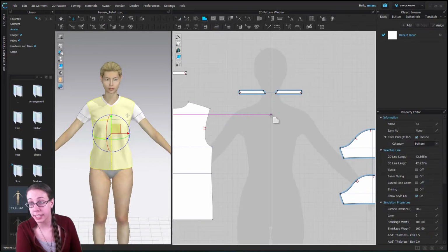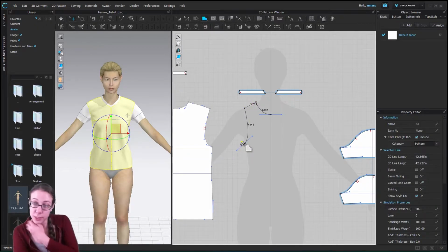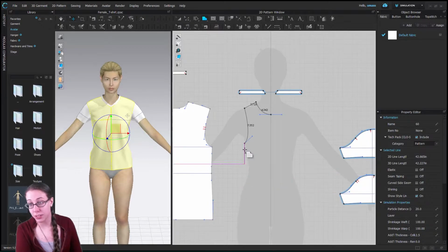And it works just like the pen tool in Illustrator, right? If you click and drag, you'll make a handle, which then affects the curve. And if you just click, you will just make anchor points, which will be just corners. Anchor points without handles are corners. Anchor points with handles are curves. You can click on handles, you can click on anchor points to get rid of the handle coming out, and do one of these.